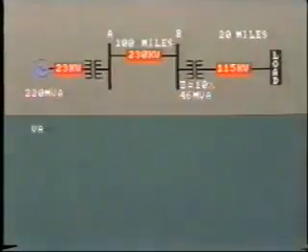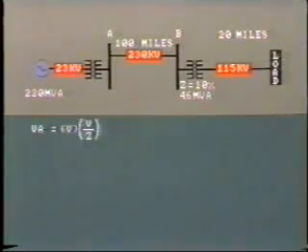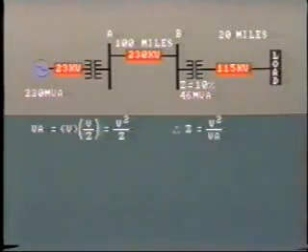But shouldn't the impedance be indicated in ohms? Well, the answer is yes and no. Not necessarily, and I'll show you what I mean. If we do need to calculate ohmic impedance, we must remember the relationships between VA, voltage, current, and impedance. First, VA, voltage times current, equals voltage times voltage over impedance Z, or V squared over Z. By transposing, we find that Z, impedance, equals V squared divided by voltamps.